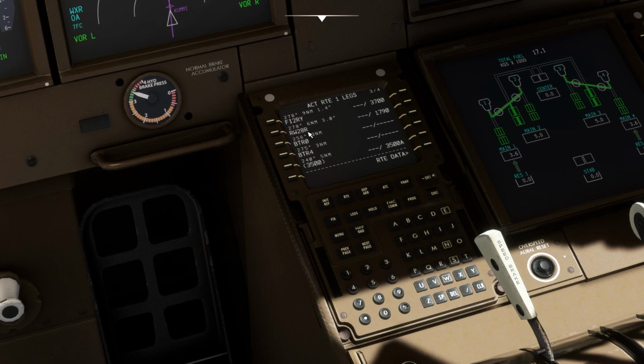So runway 28 right is coming over here, and this is the runway that I will be using to land. Before this FI2RY, the altitude coming over here is 3,700 feet. Another point I would like to clear is that Islamabad International Airport is 1,790 feet above sea level, so that's why you can see 1790 over here. This is the altitude that I will be setting in the MCP, and once I start my descent, the plane will start to descend to 3,700 feet.